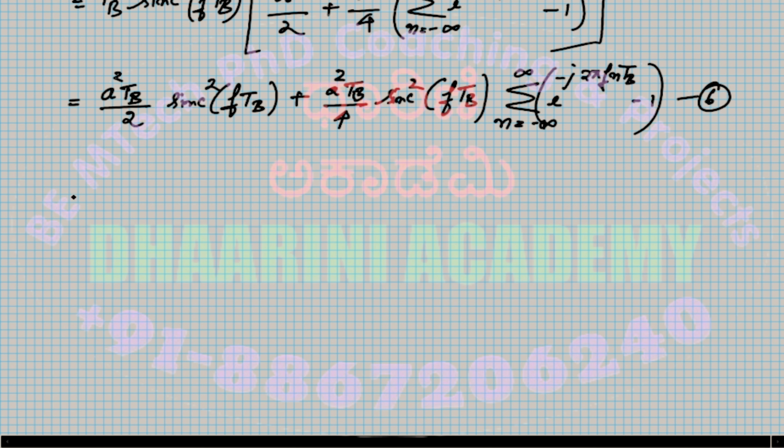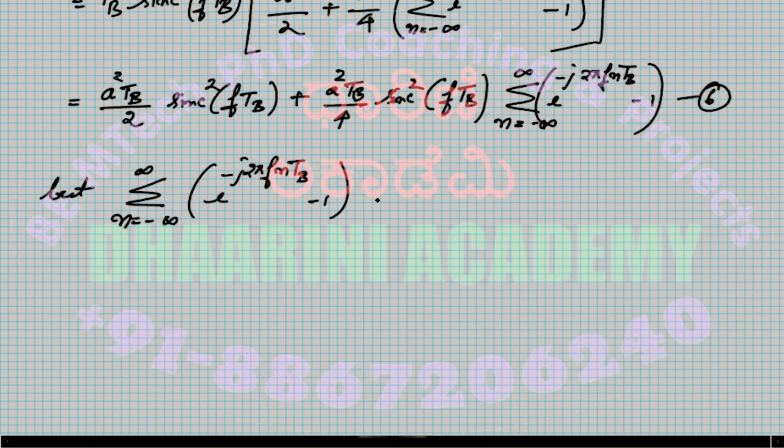From there, you can write one thing: this term, the summation n equal to minus infinity to plus infinity, e to the power minus j 2 pi f n TB, can be simply replaced as 1 by TB into summation, changing the variable, maybe m equal to minus infinity to plus infinity, delta function, impulse function of f minus m divided by TB.